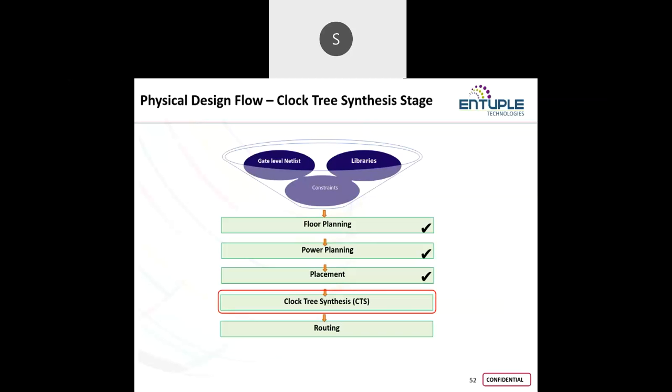I can't say a percentage, but it depends on how complex your design is. If it is not that complex, the power variation will not be that much. If it is a complex design, then you might have more cells in the design, so obviously the power consumption will show a difference between the reports checked in synthesis and after synthesis. So, did I answer your query?